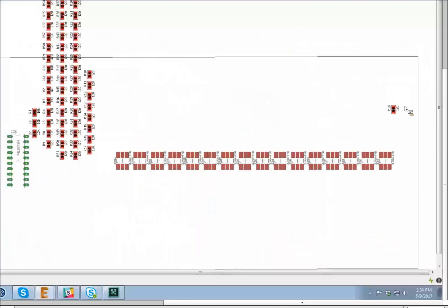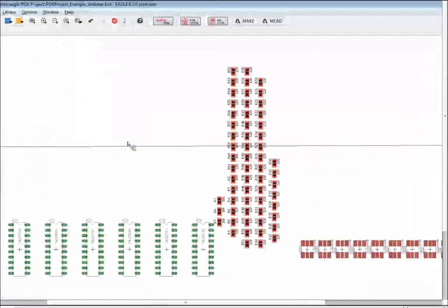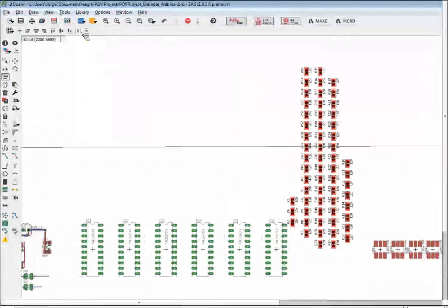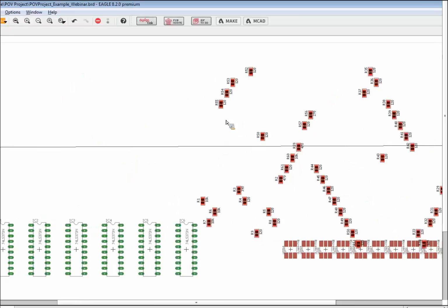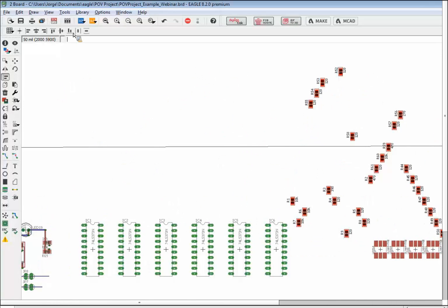So I'll click on group again. We still have our group defined, it remembers. We'll select alignment. We'll distribute these horizontally. You'll see that you get everything moved so that we're in sequential order for the most part. And now we can do something like a center line alignment, which I think is the best choice here.